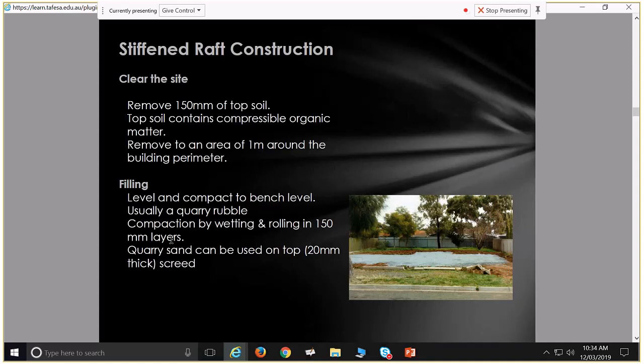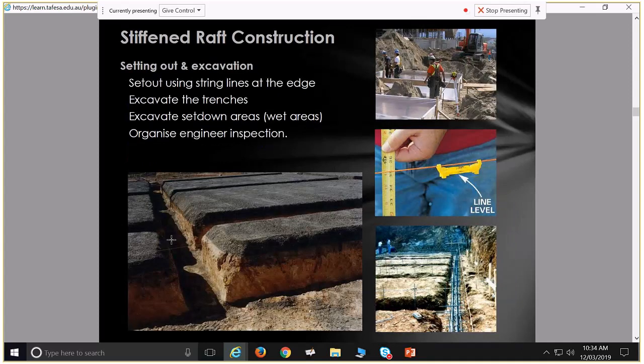And then for your top bit, you use a bit of quarry sand, or crusher fines, on top of that, both to protect this plastic stuff and also to form a really nice top for cutting out your beams like this. So this section there, that's quarry sand. Quarry sand, dolomite, crusher fines, same thing, three different names. So that's on a fairly clayey sort of loam on top, but you end up forming nice beams.